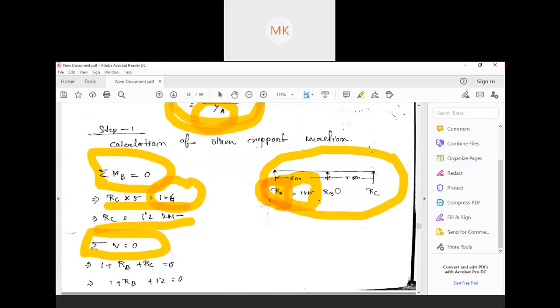Yeah, sir, but we're using determinate calculation to calculate an indeterminate beam. No, no. Summation of force. I have already said that condition. You have to assume this beam as a free beam, as there is no support and all these things. That's why we are just drawing this arrow. See, just the arrow mark. We remove the support. Whatever the support, we need to remove that.